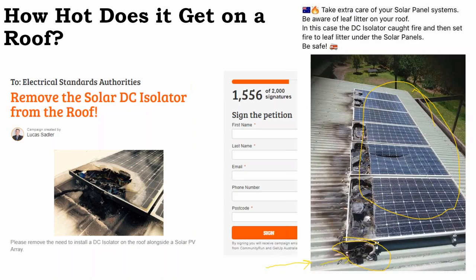And this more generalized balance of system material might only have a 60 C or a 75 C temperature rating, whereas everything else, your solar cable, your solar panels, the inverter, everything else in the system is designed with a 90 C temperature rating.